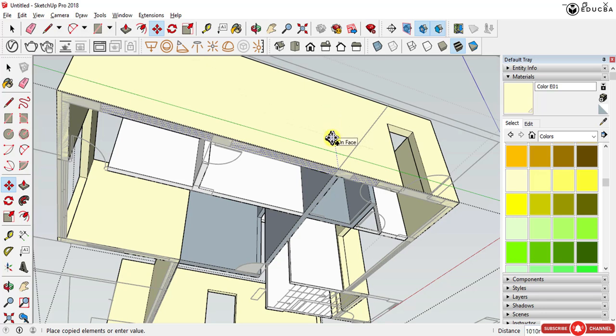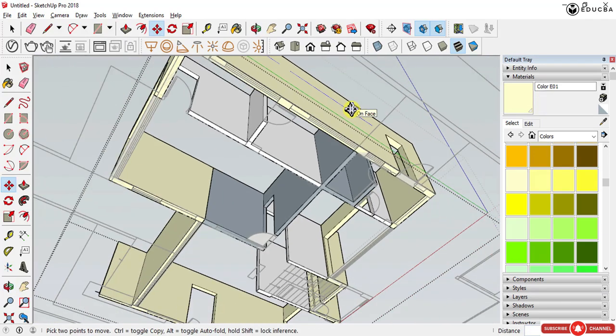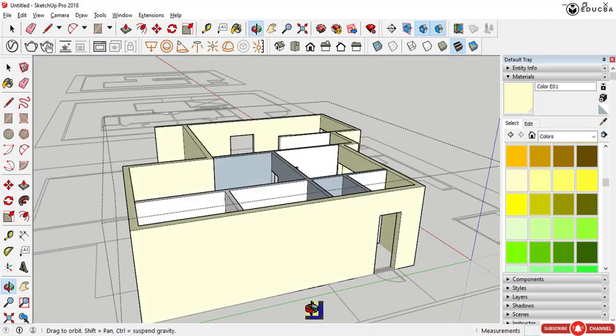So the sill level is going to be for us 1000 mm. I am doing an input of 1000, and another one to 2200. If you can see, there are slight traces of the line. When you pull out, you can see here there are traces of the line. Now if I'm trying to connect them and I come down with the down arrow, you can see it is prompting me.